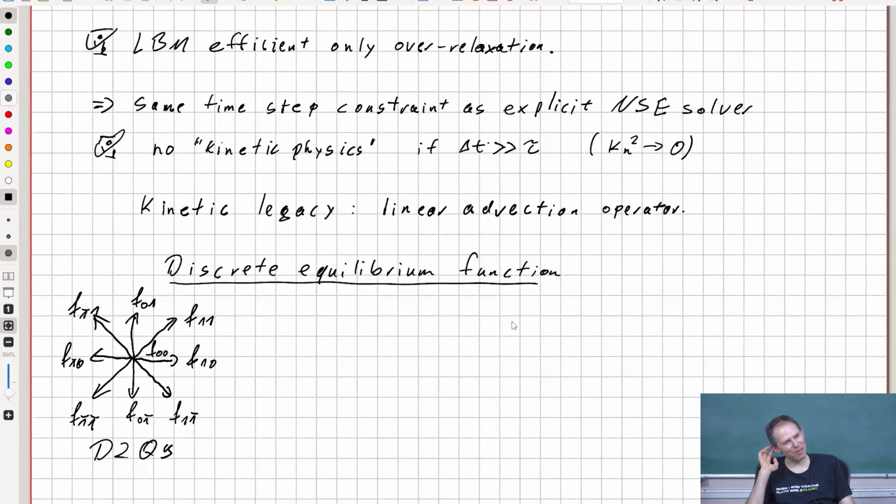It's the outcome of that. One more question: in this Lattice-Boltzmann method, the idea is to advect these particles. Advect, in what sense? Like you stream, you collide. Yeah, but this is not advection. Advection is when the macroscopic arising velocity field is transporting something. That's advection. Okay, so we have a collision operator, and we have advection or streaming operation. Yes, we have streaming.